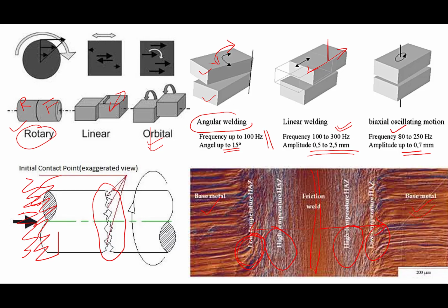That's one thing. At the same time, you can also see that the grains are getting reoriented or elongated or deformed in a particular direction. So this is the zone where you have the effect of both. You can call this a thermomechanically affected zone, this TMAZ. So one zone is the heat affected zone, then the thermomechanically affected zone, and then the weld interface directly.